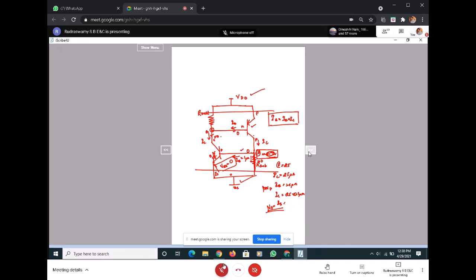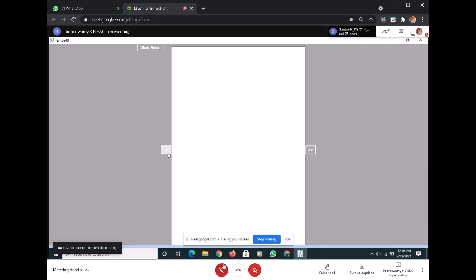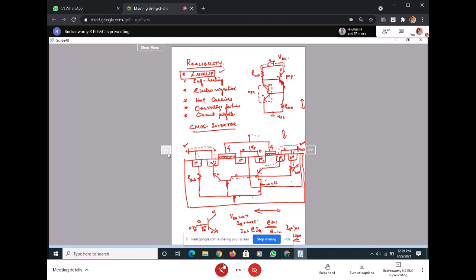And there are some methodologies for how to minimize the resistance in the substrate and the well. There are some mechanisms to minimize the resistance, but the moment I reduce the substrate resistance or the N-well resistance, I can ensure the latch-up problem can be worked around. This is one of the methods. Hope this is fine now. I should ensure only this now.